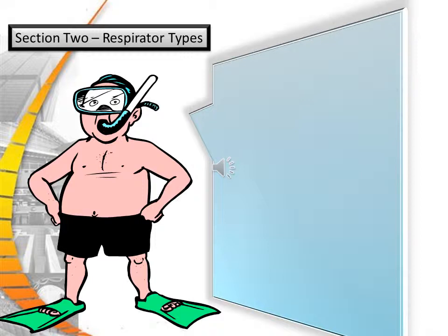These respirators are disposable and typically used for one day or one shift. Half-face cartridge respirators can provide protection against chemicals with the correct cartridge. Full-face cartridge respirators provide eye protection from irritating chemicals and fit tighter, making them more protective than half-face respirators.